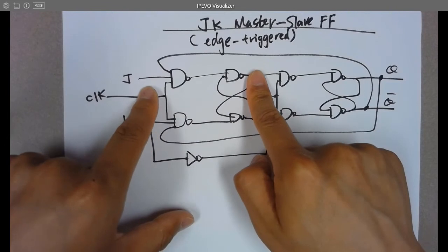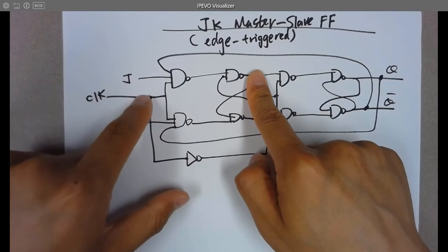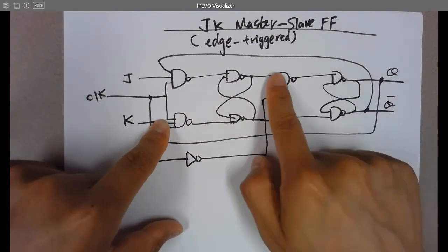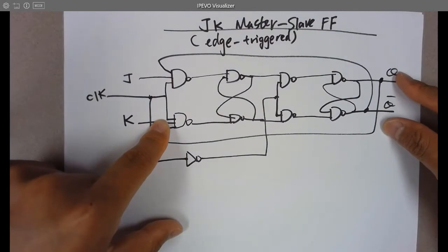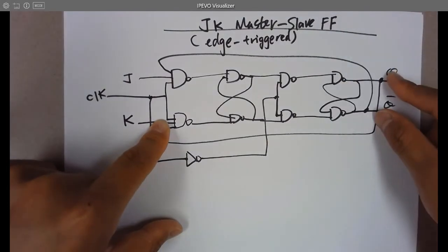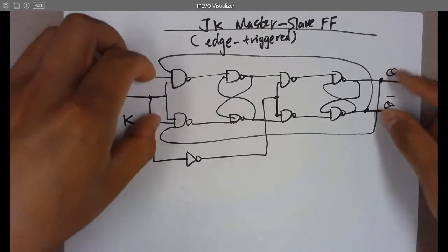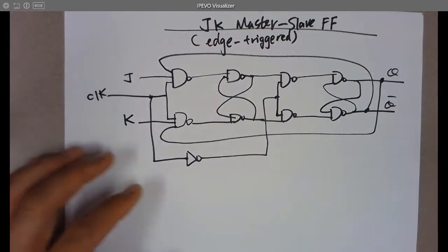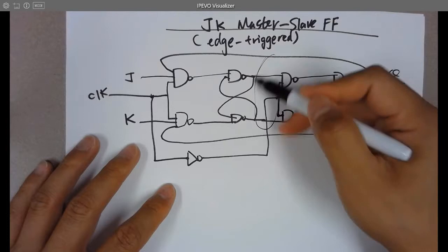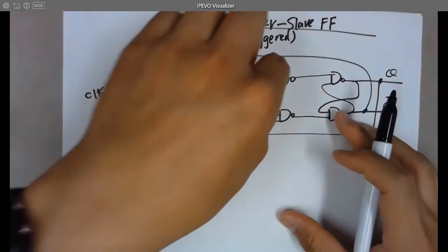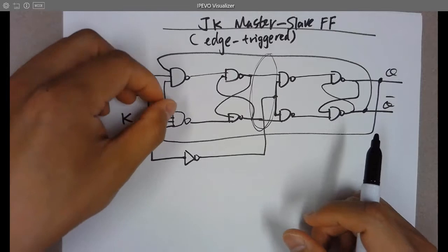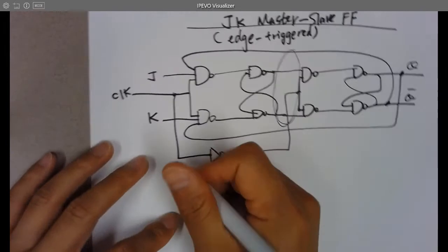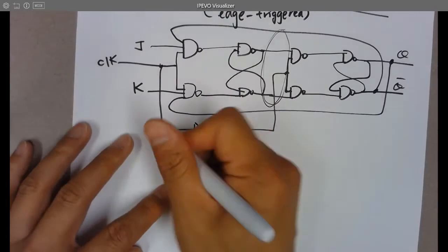Okay, and next you see this one has a falling edge, and after getting inverted, you get a 1 here, so this part is enabled, so the data can go through. So when the data is going through to the output, this one is disabled, so the input won't affect the result at the output because there are two steps. It's like a buffering. So this part is like a buffering area. You store something here temporarily, then close the door and deliver that to here. Things like that. And there are some properties I need to add as a description.